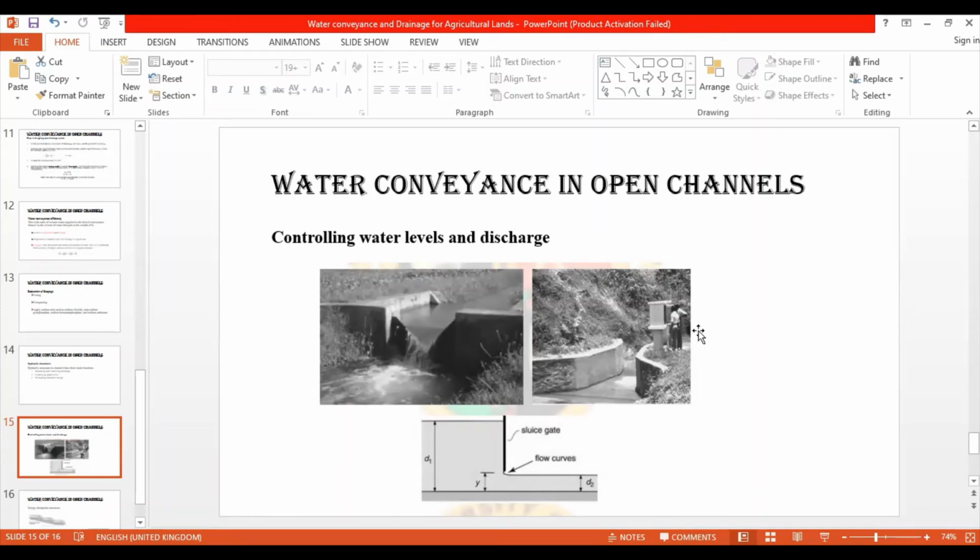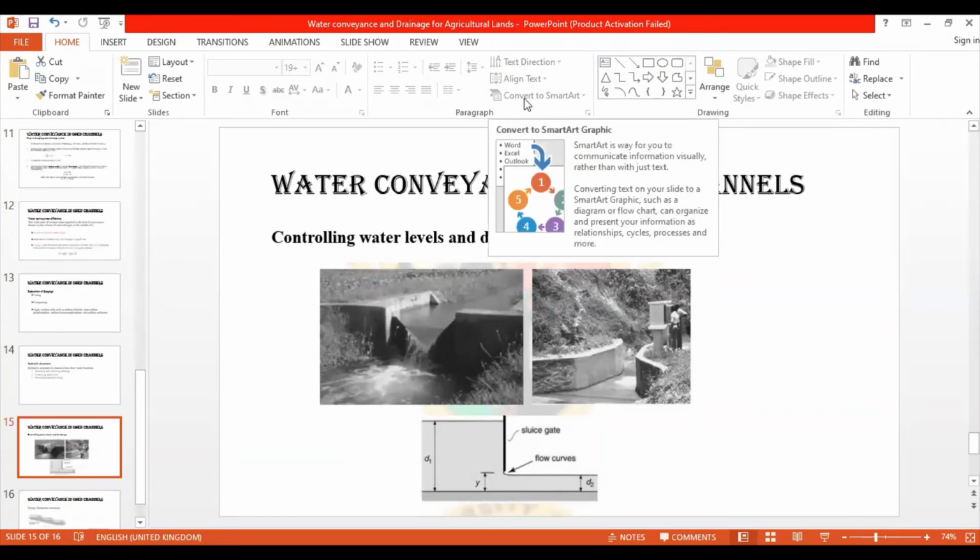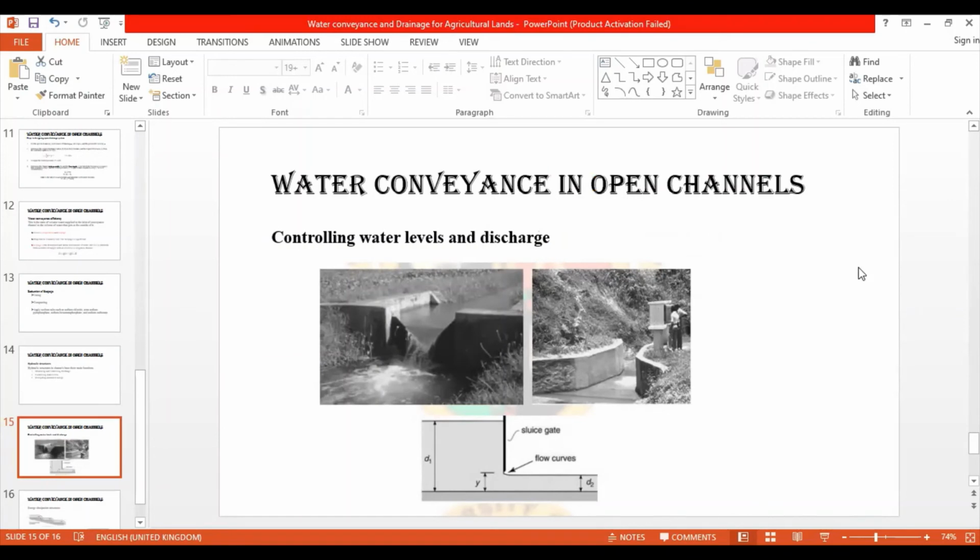You slide it open and you slide it closed, so that if you want to stop irrigating in that field, you simply slide it and it closes that channel, and the water proceeds in the other direction to water the second field. When your second field is done, you close that as well, until all your fields are irrigated. We call that a sluice gate.